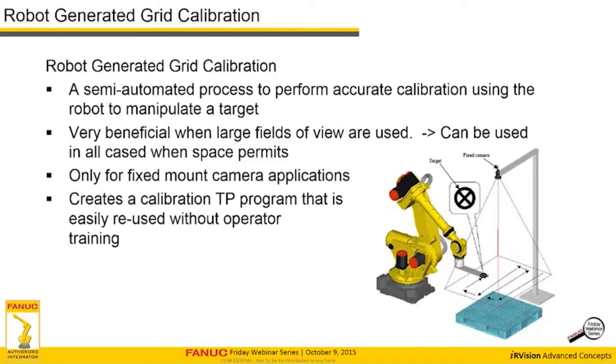Just a TP program that executes on the teach pendant. And a side issue is, as promised, it does deliver a tool center point. It delivers the TCP of the target, just like the IR calibration automated TCP setting would deliver in that package.